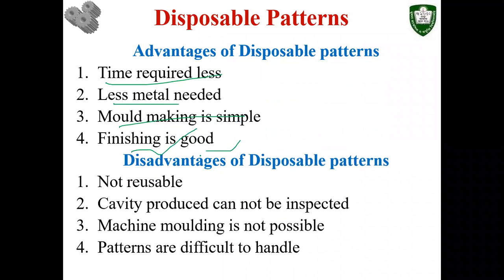The disadvantages are that they are not reusable. You cannot use them again and again. The cavity produced cannot be inspected, which I have already talked about. Automation is kind of difficult, and the patterns are difficult to handle because they are fragile. They can break very easily.